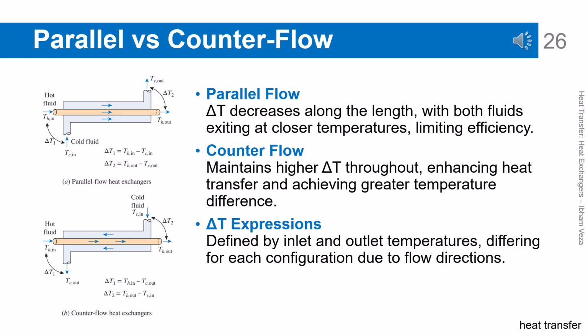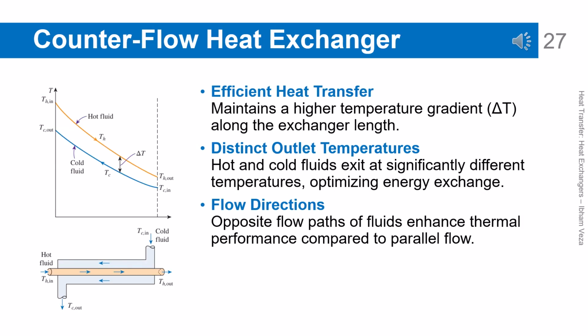Parallel versus counterflow heat exchangers. This comparison shows the fundamental difference between parallel flow and counterflow. In parallel flow, the temperature difference decreases quickly, resulting in lower efficiency. In counterflow, the temperature difference can be maintained at a higher level along the exchanger. The inlet and outlet temperature difference expressions are also different for both configurations. This concept forms the basis of the LMTD method.